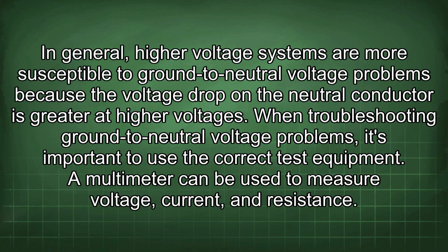In general, higher voltage systems are more susceptible to ground to neutral voltage problems because the voltage drop on the neutral conductor is greater at higher voltages. When troubleshooting ground to neutral voltage problems, it's important to use the correct test equipment.